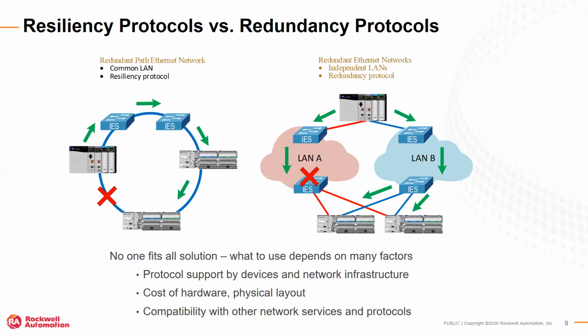So they are truly, truly independent and truly redundant pathways. Ultimately, what is happening is we are sending the data out of 2 ports, and whoever gets to the end device first is the winner. The other data is thrown out. So that's what separates it from a true ring.